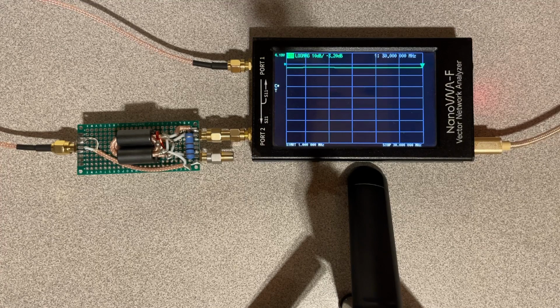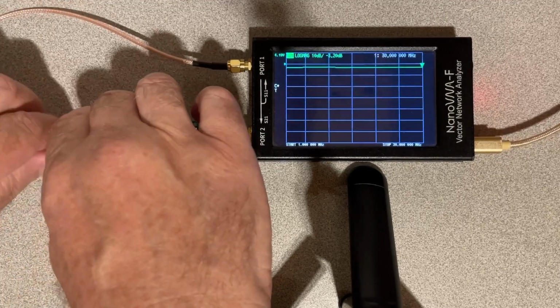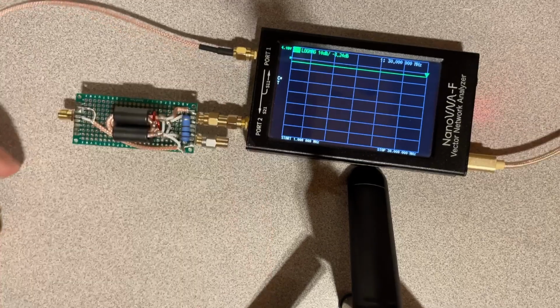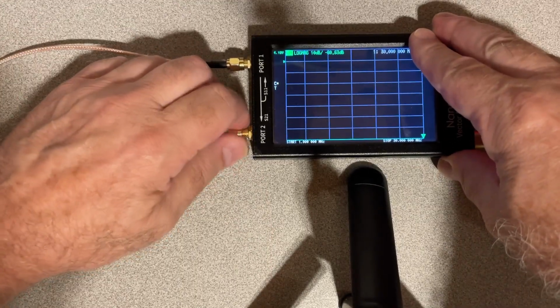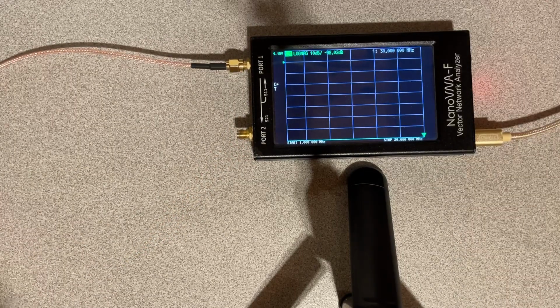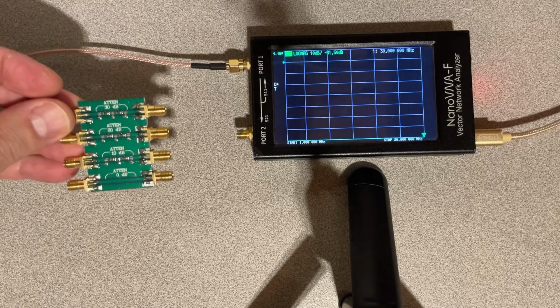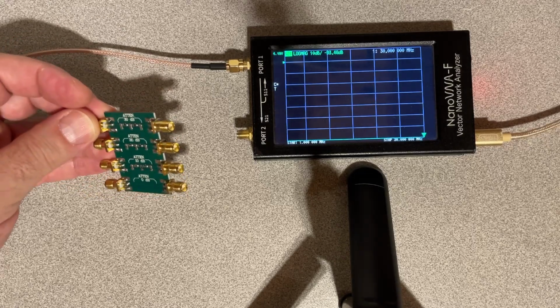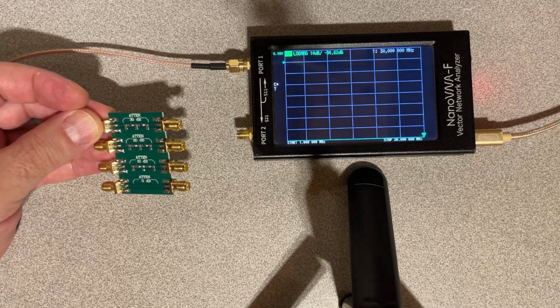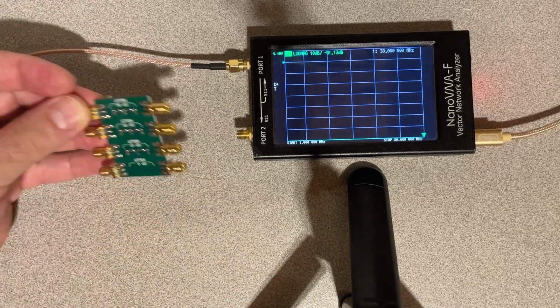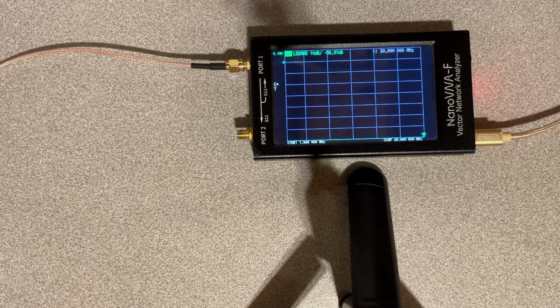I'm satisfied with that. And to check your instrument, it's always a good idea to see if we're getting an accurate measurement on insertion loss. Just bear with me here as I set this up with an attenuator. So here I have an attenuator that has minus 0 dB all the way to minus 30 dB. So we can use this to see how accurate our measurements are.